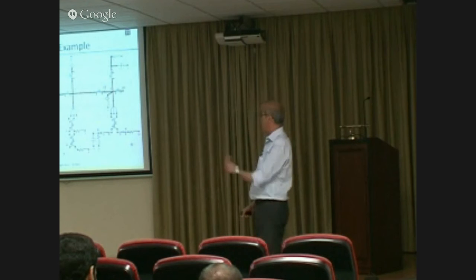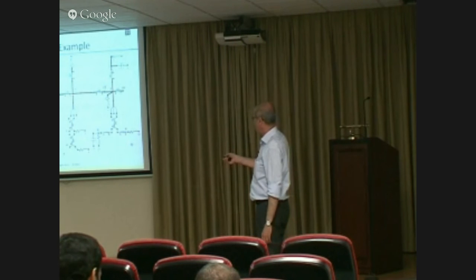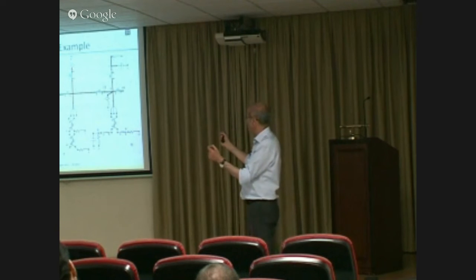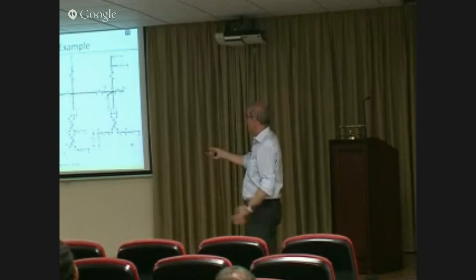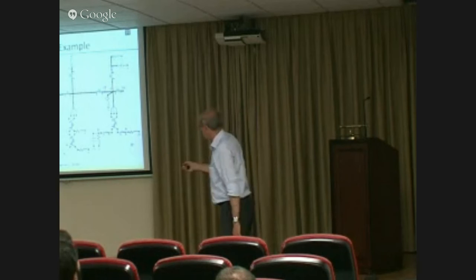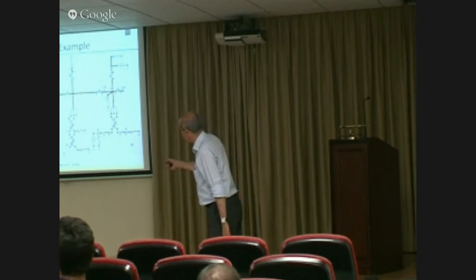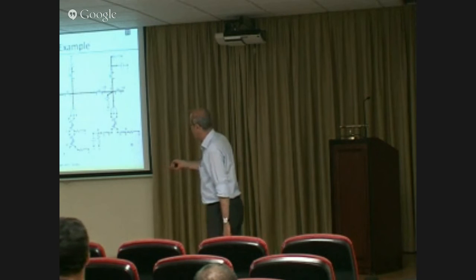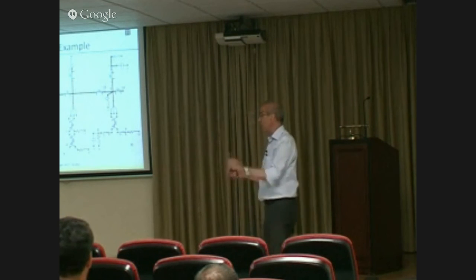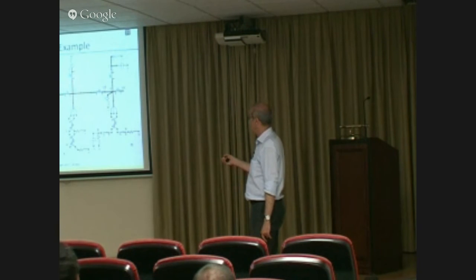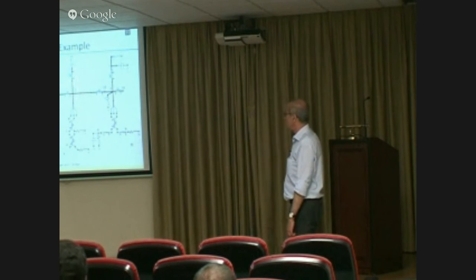And those 4 are the ones corresponding to phase AB and phase AB at the two ends of this line 2 to 5. And more interestingly, if you look at the ratio of this to that, I don't know if you can tell, but this is 1500, this is 500. So the ratio is 1 to 3 because the distance of the actual fault from this end is 1/3 of this line length of 2 to 5.